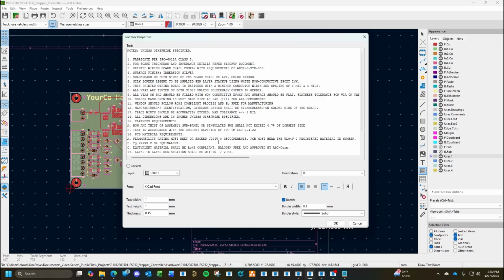A lot of the newer ways of doing things, you don't really need to put the fab notes in the PCB Gerber files anymore. It's helpful, but not really required anymore. A lot of times manufacturing vendors are more than okay with separate files, like a PCB fabrication document, which we'll get into in more detail later in other videos maybe. When I start using Circuit Studio, for separate documentation, we can create a packet, but it's just as easy to throw it into the fabrication notes.